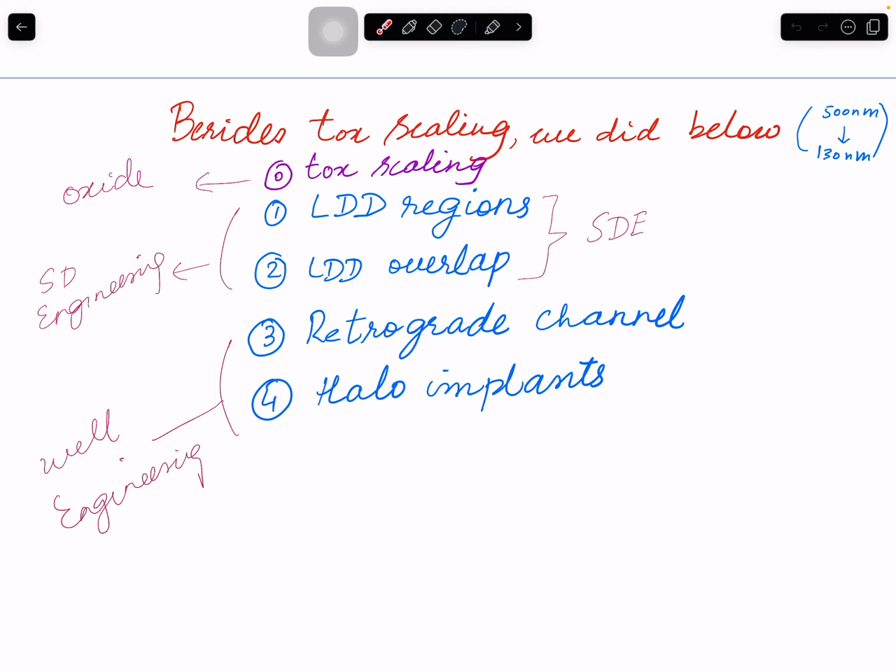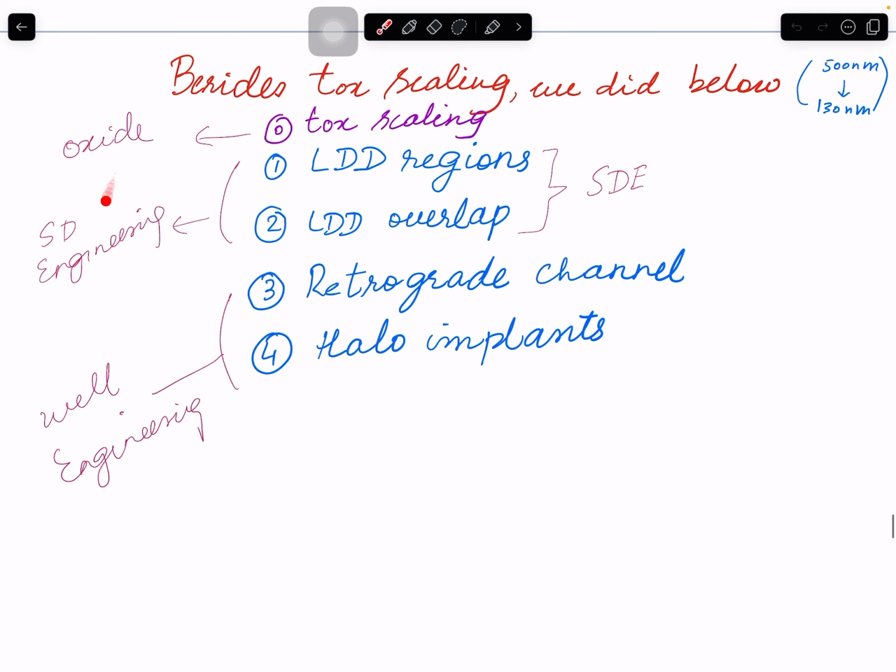Short channels, when they are too small, it's very hard to improve the current. So the on current amount needs to keep increasing, the off current needs to decrease, and we need to stabilize the voltage threshold. We control the voltage threshold, not the shorting of the channel. All right, so that's where things change in these three areas.